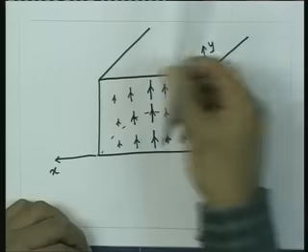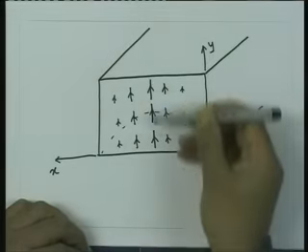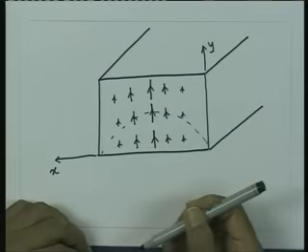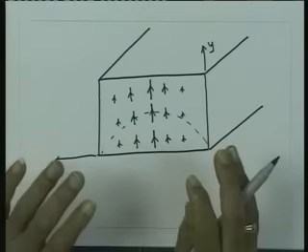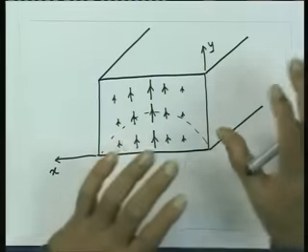By looking at the field distribution, it becomes clear that if you create a mechanism by which the field will be maximum at this place, then that excitation will support this field, and the mode which gets excited inside the waveguide will be the TE10 mode, provided the size of the waveguide is such that the TE10 mode propagates.